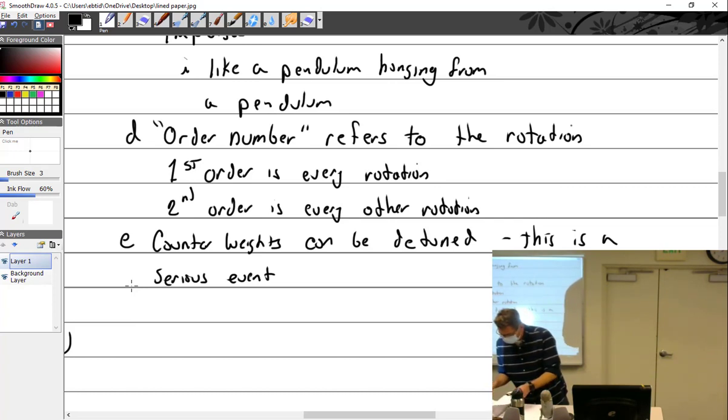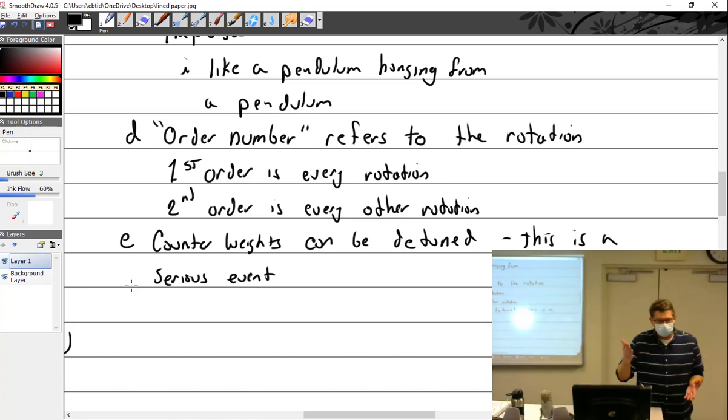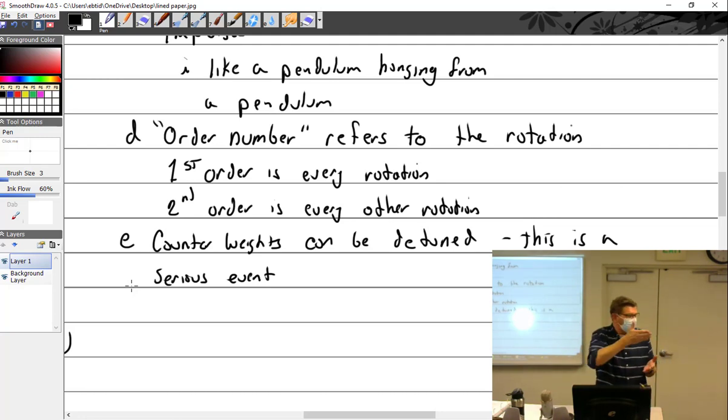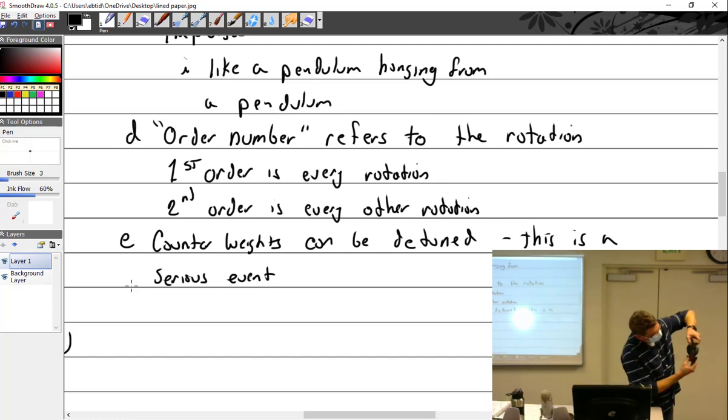It was in tons. I thought I had it on here. How many tons of force these take, because they're roller bearings, or they're rollers, and the surface area is so infinitesimally small that it doesn't take much of a hit for tons of force to go in there, and it dents it. So you put a dent in the bushing, and a lot of times you can feel it if you hang it and you go through it, and as you do the pendulum, you can feel it drop into a little dent. You go, oh, they've been detuned.